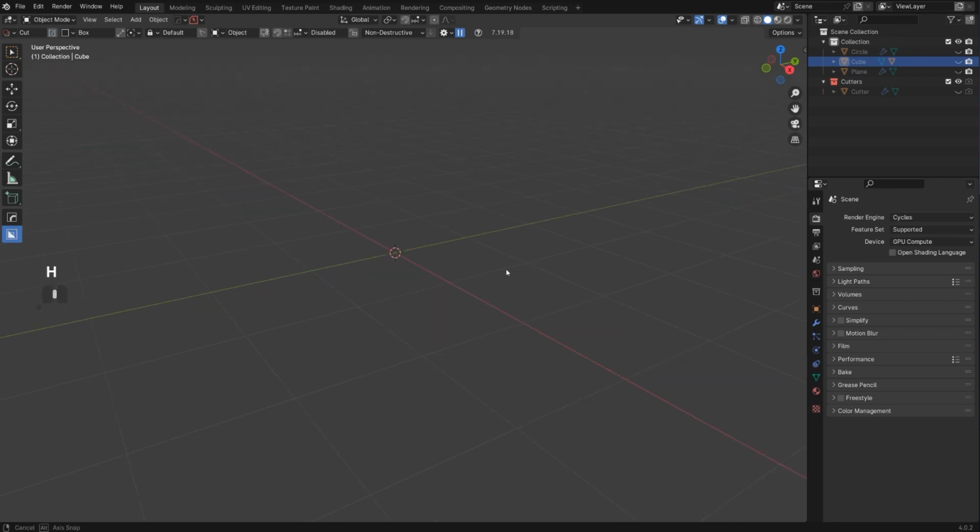And there's one more workflow, which is very different. You simply create a new topology on top of what you already created. So let's say you have a very complex Boolean shape, or you have a sculpted mesh, or you have an import from CAD software, which is going to be really, really messy in terms of topology. And you want to retopologize it, so you lay a new layer of topology on top of that mesh. Now, since the previous method was Boolean to quads, you may ask the question, well, why would we need to retopologize Booleans?